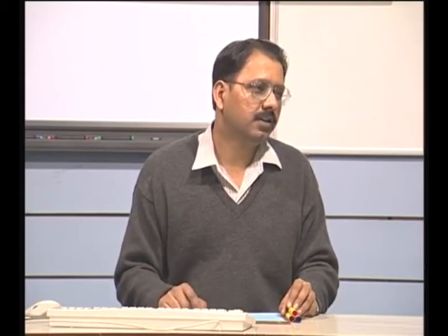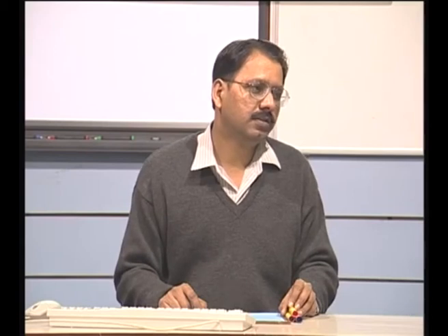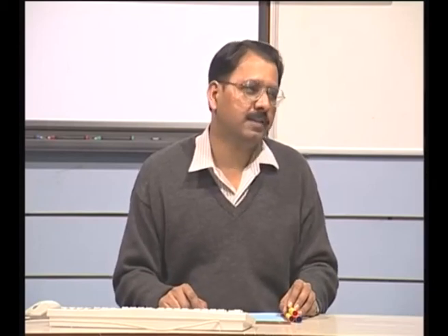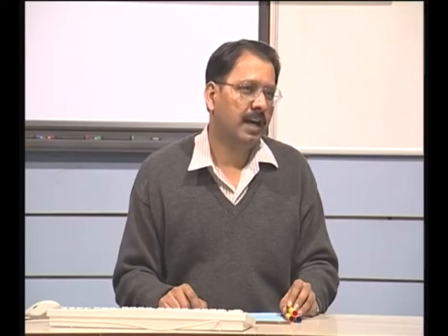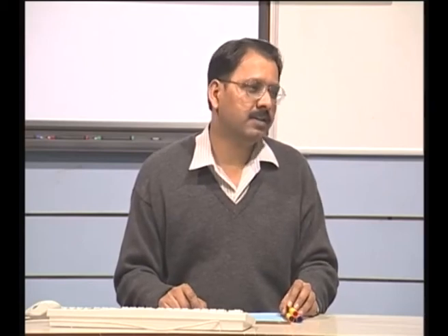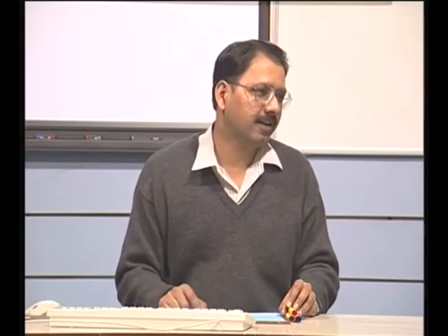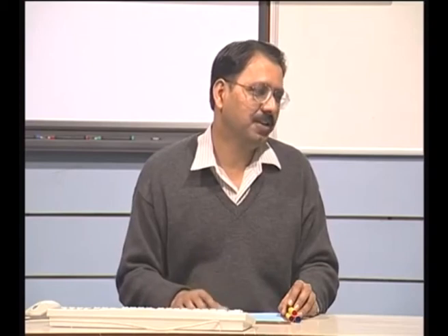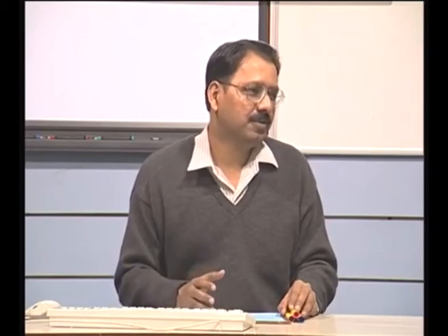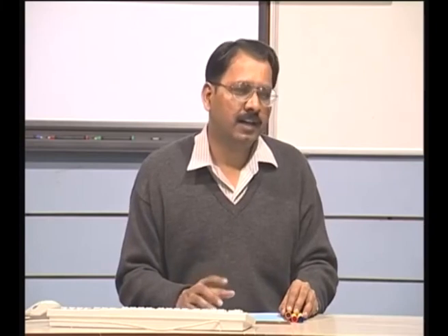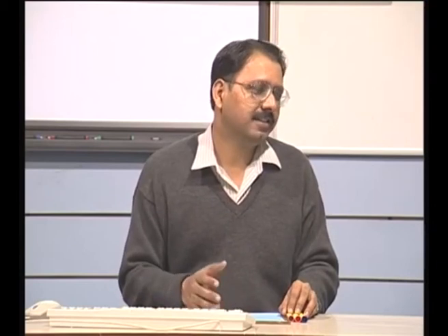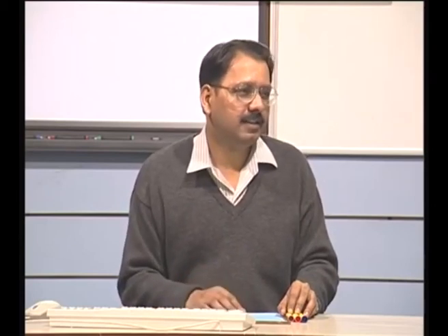Boundary representation, like Coons patch, we are using the Coons patch by the boundary curves. The only advantage of using a Coons patch kind of thing is, suppose I want to represent a surface. One boundary curve is a straight line, another boundary is a circular arc, third is a Bezier curve, fourth is, let us say, a B-spline curve. Still I can get a very good surface which interpolates this. So, you can use any combination, it does not prevent you from using a specific form. But I will come back later that one form can be converted to another. That can be very easily done.